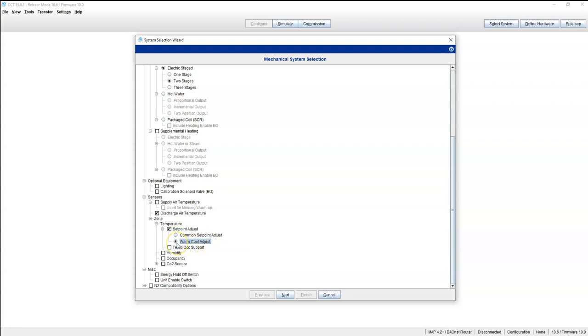Warm cool adjust, that's a relative range. That's +1 degree, +2 degrees, +3 degrees, or -1 degrees, -2 degrees, -3 degrees. Whatever range you set in there, you have a network set point of, let's just say 70 degrees, and you give the customer an option up and down 5 degrees. The customer usually does not know what the actual set point is. All they know is, do I want it warmer or cooler?